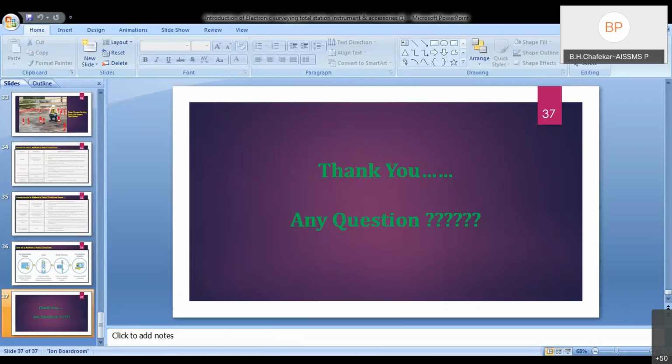Okay. I will post this answer on the chat box also. The grid north is a navigational term referring to the direction northwards along the grid lines. But in contrast, true north is the direction to the North Pole, and there is magnetic north. While using the total station or robotic total station, we consider the curvature of Earth. So in that case, we have to consider the navigational terms. The angle calculated from the true north or magnetic north or grid north will be accurate by considering curvature and any other navigational terms.